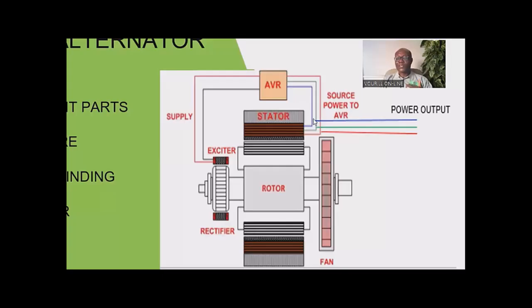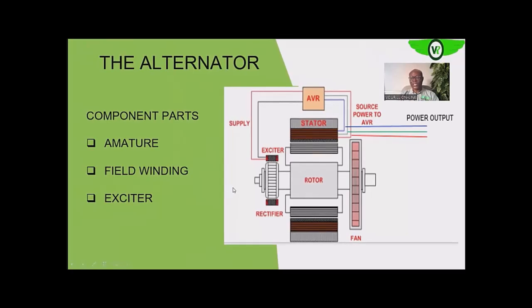Also, it is fed from the exciter transformer, then it converts whatever is fed into it into regulated DC voltage that will be sent to the field by slip rings. Okay, so in that case, the kind of generator that we'll be having will not be brushless like this. It will have the brush type excitation system. We have another training you can check out for more on this. You can check out our training on generators, the alternators, on electrical machines, where it is explained in detail.